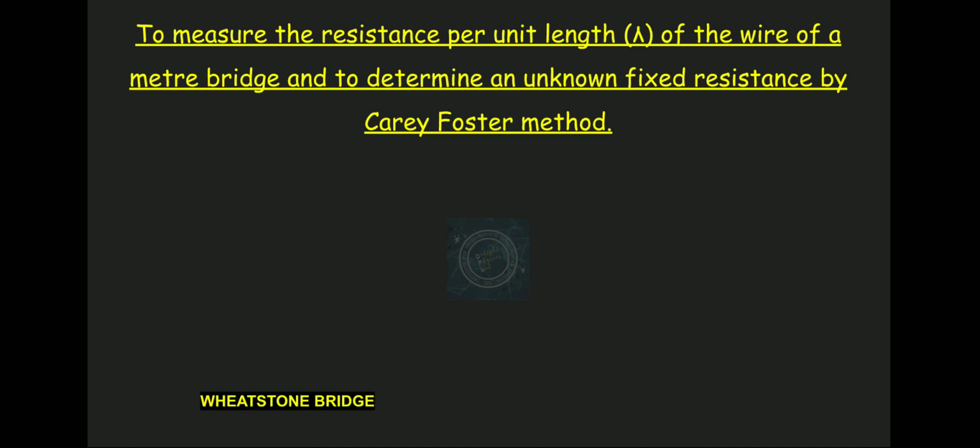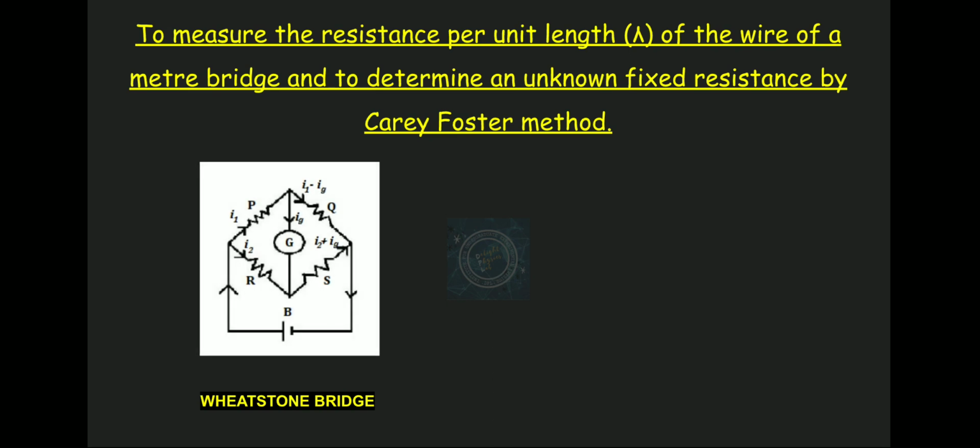Well, what's the Wheatstone bridge? That's very elementary. I have shown a diagram here, which is one of the most conventional diagrams around. There are four resistance arms. We'll call them ratio arms. The top left arm contains resistance P conventionally. The top right has Q, the bottom left has R, the bottom right has S, and the battery B is causing a current to flow through this circuit.